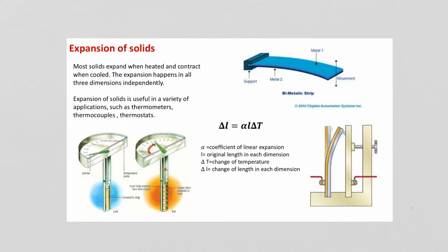Another application of a bimetal strip device is a circuit breaker for an electrical circuit. Once the temperature here increases enough, this strip is going to disconnect the circuit, and when the temperature drops, the strip will close the circuit.